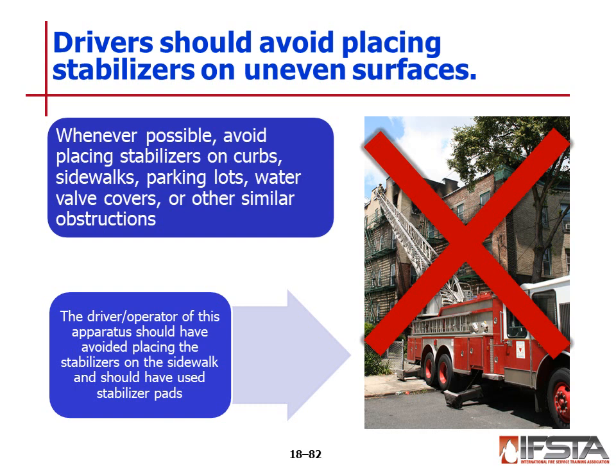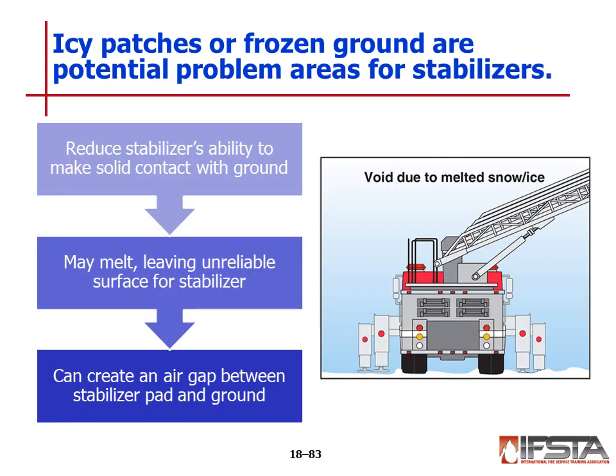Uneven roadways, sand, and gravel should be avoided. If objects are already damaged or weakened, they are not candidates for the weight and the stress that the apparatus will place upon them. Rather than deploying stabilizers on an unsafe, potentially unsafe surface, reposition the apparatus.